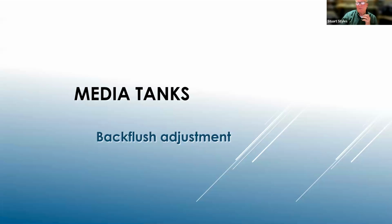So the biggest thing that I run into on the sand media tanks is this backflush adjustment, getting the correct flow rate based on the manufacturer's recommendations, and you can change that on your backflow valve. And then making sure that you have adequate pump capacity and pressure, so that when you do go into a backflush mode, the pressure stays high enough to keep the backflush going and get backflush to occur, but also that you have plenty of pressure going out to the rest of the system, so that you don't just have a horrible drop in your uniformity values just because you're having to go through a backflush cycle.